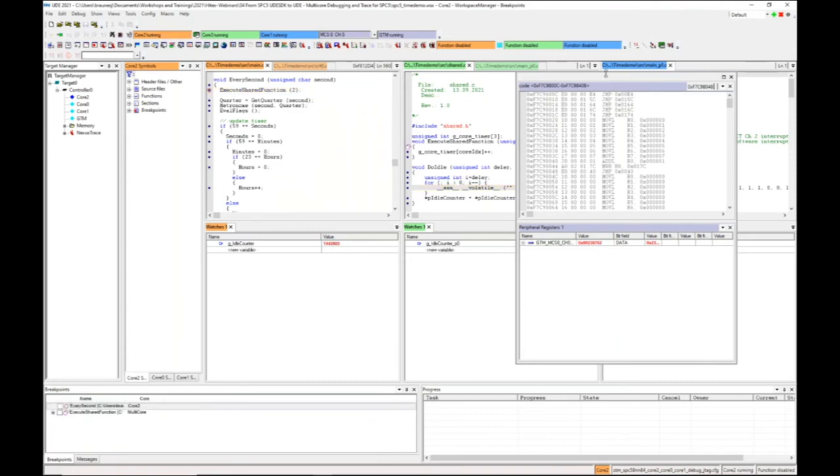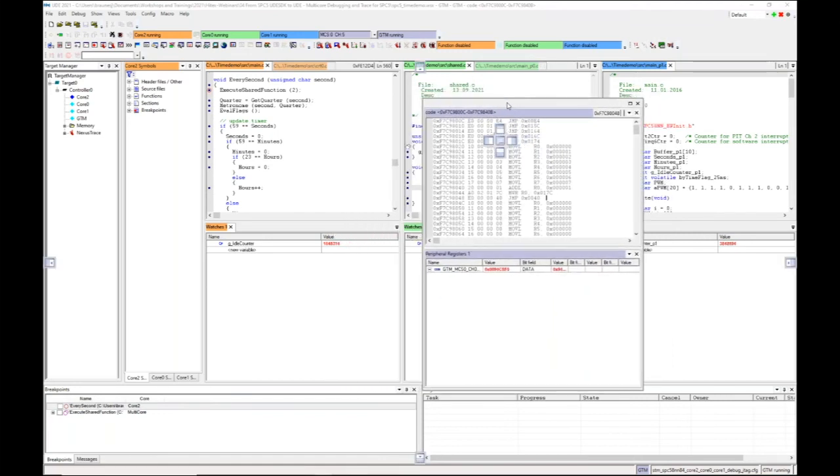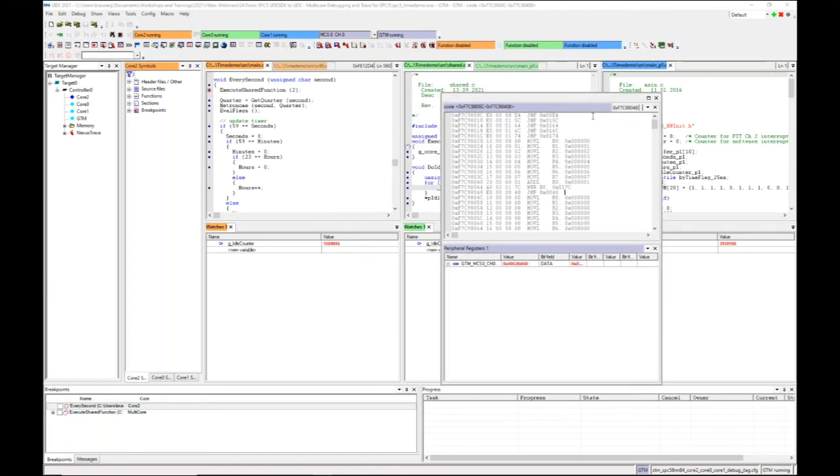That's basically what you can expect from debugging GTM. For a real debugging of the GTM, only trace can be used, and I'd like to show it at the very end of this webinar how it works. But before we try to trace GTM, I'd like to show you how to trace the SPC5 in general. I mentioned before there is a Nexus Class 3 Plus implementation available on most of the SPC5 devices, which needs to be configured by the tool to get out some trace information. And now I'd like to show you how it looks.